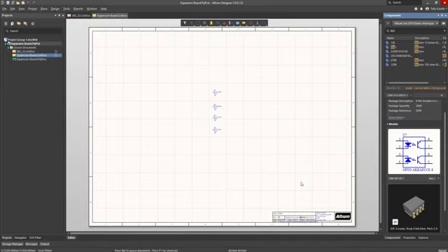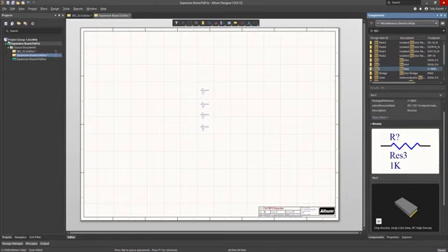The integrated library files have an extension of .intlib and contain both schematic and PCB footprints. Note, there can also be local project-related libraries. These would be available in the project's list of files. However, we do not have any project-related libraries for this project.